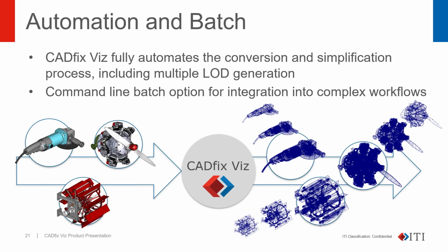So automation and batch, again, I've talked about this. You'll see this once you get to the product. There's definitely automation just within the GUI in terms of loading up a model, having these different levels of detail that you have preset with some of these options, and just generating meshes and then deciding which one is most appropriate and experimenting around with those options, and maybe getting a finely tuned config file that you always use. And then you can also do that entire sequence of things in a command line batch option. So this could all be integrated into maybe a workflow of taking MCAD models down to different resolutions for the VR, AR, MR workspace.